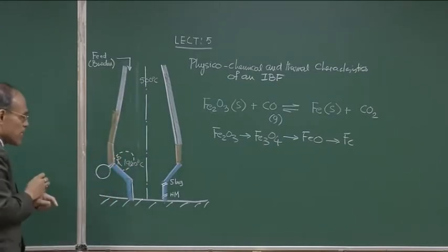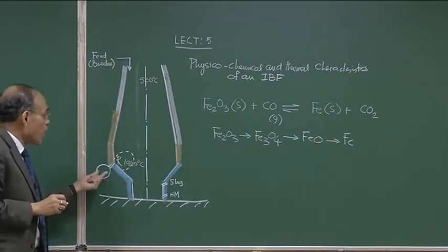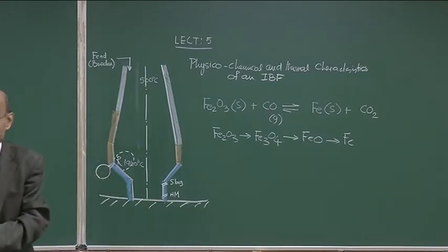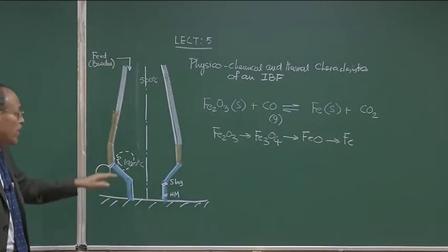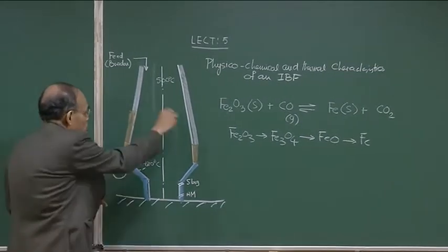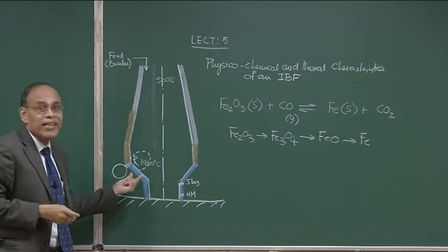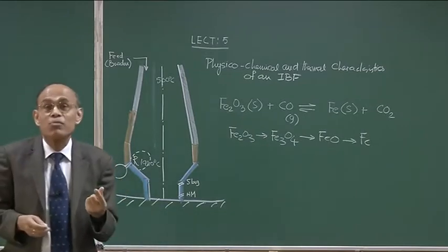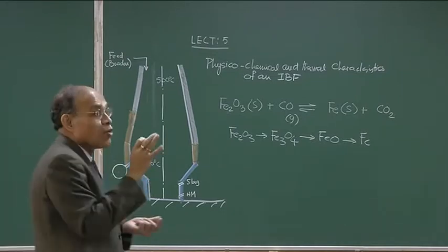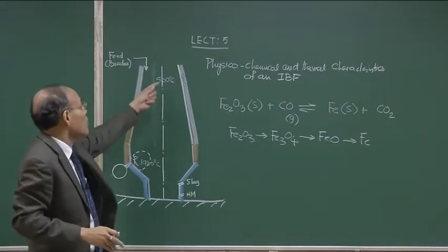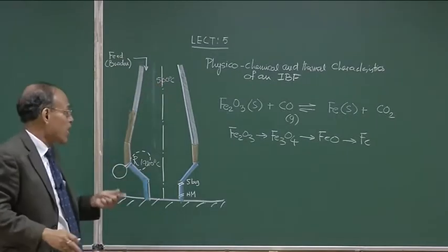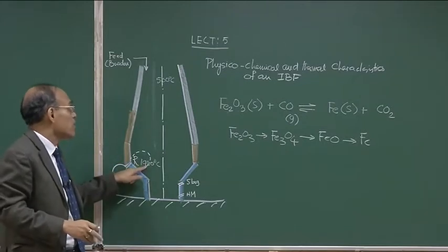As a result of which we can assume that we have a high temperature scenario, and also, as I have indicated, and we can get this information from the Ellingham diagram also, that at such high temperature we will never get any carbon rich bath or carbon rich system, a system which is filled up with a lot of excess carbon. We will never get carbon dioxide, because carbon dioxide is a phase which is relatively stable at lower temperature, close to room temperature, or maybe at very low temperature, okay. But more importantly, the relative stability of carbon monoxide is much higher at higher temperature than carbon dioxide.